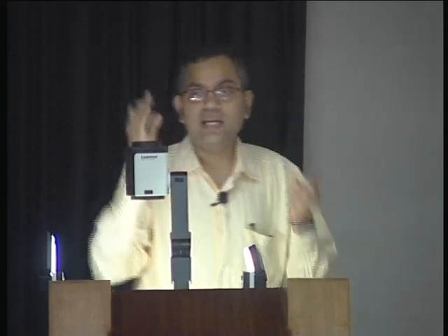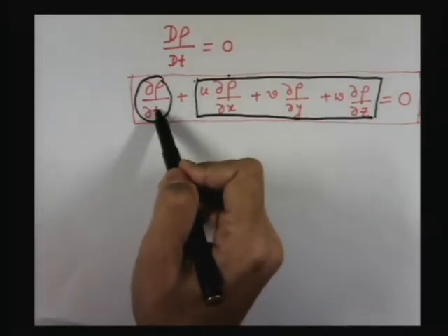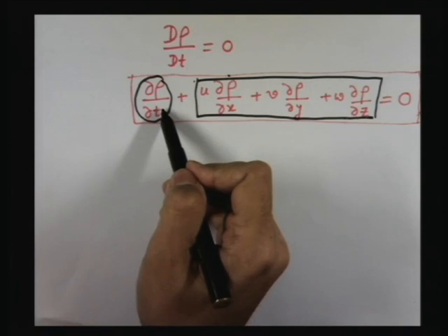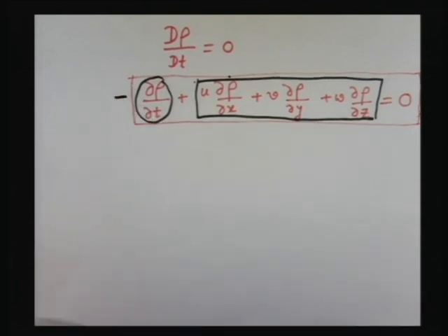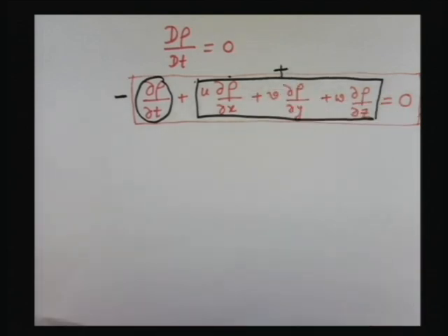So when it is changing in a control volume from liquid to vapor, let us say it is expanding. So at a given location, the density is decreasing with respect to time. So this is negative. This is compensated by this advection term which is positive. So that must be compensated by some transport across the faces of the control volume, so that this net term is 0. That means that you have rho at a given location changing with time, but still it is acting like an incompressible flow.